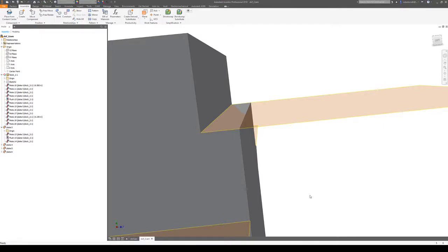But if you think about it, that tends to be pretty common in FEA anyway. We're often simplifying structures and changing them a little bit to make them behave better as analytical models, understanding that the results in that area, say where these two things meet, may not be as realistic as they were before, but overall the displacements of the structure, the stresses in the plate structure, for example, and the deflection at the end would still be good.